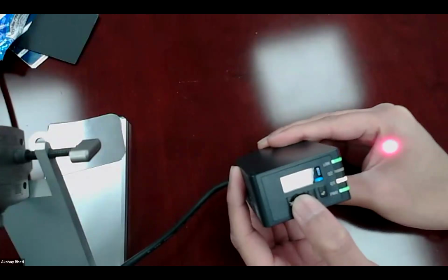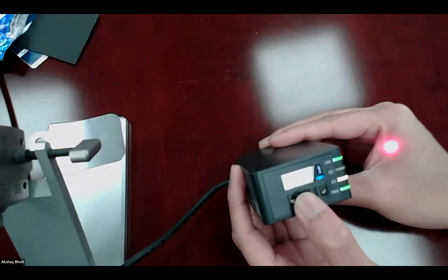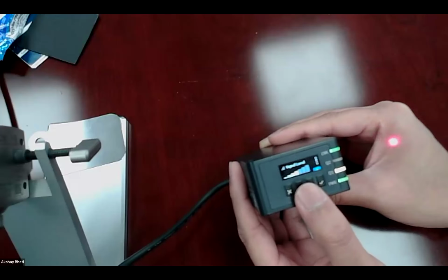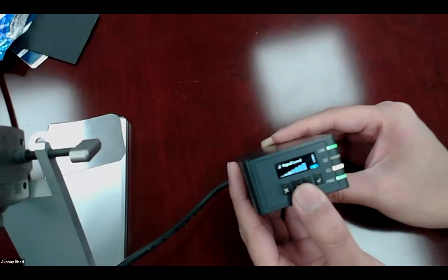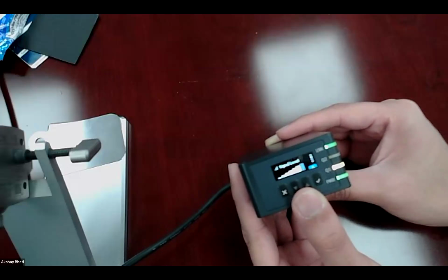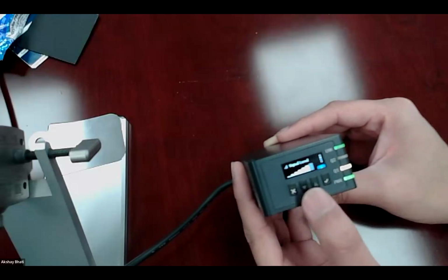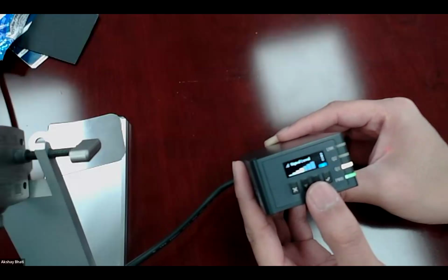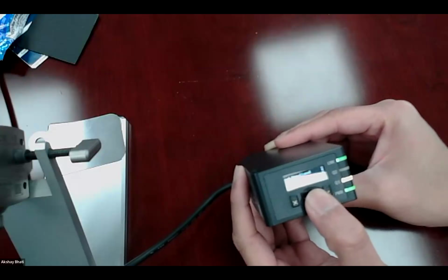It has a few modes which you can configure through the sensor itself. For example, first thing is you can check the signal level. If I am on black, the signal level goes down because all of the light is absorbed. If I look at white, the signal level goes up. So it's good in troubleshooting where the sensor is not working well. Then you can get the signal level intensity from the sensor itself.